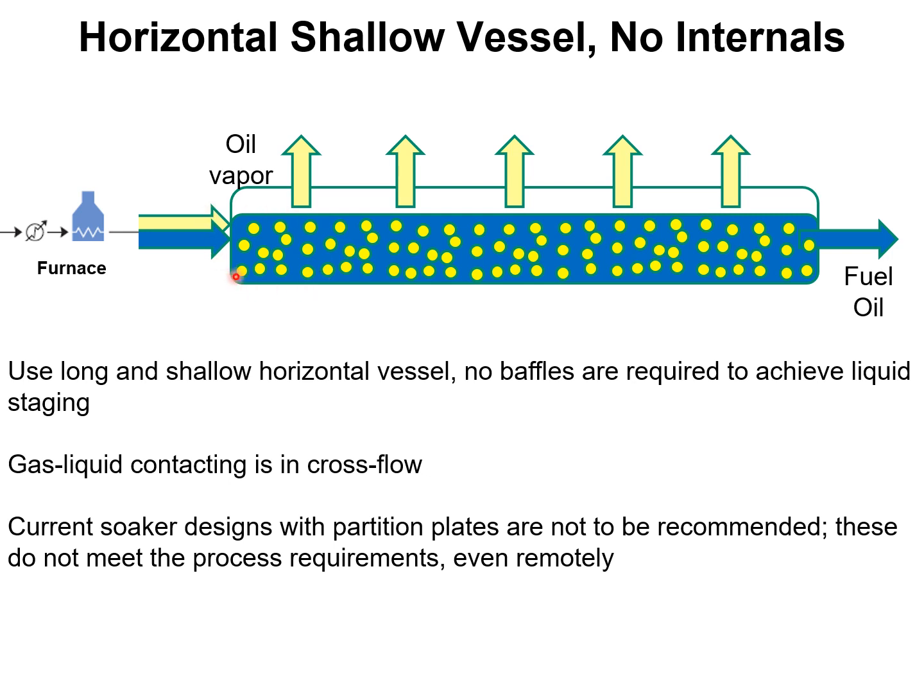So if the H divided by D ratio is 1, we will have approximately one well-mixed stage. So in this drawing here, we would have, say, one well-mixed stage, two, 3, 4, and 5, and say between 5 to 6 well-mixed stages would correspond to plug flow of the liquid phase.